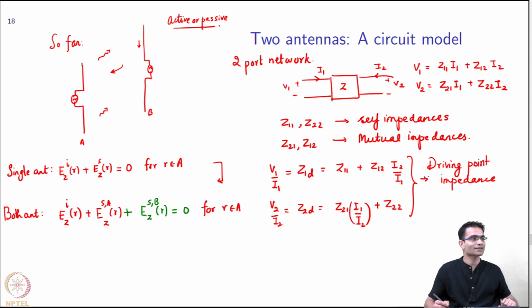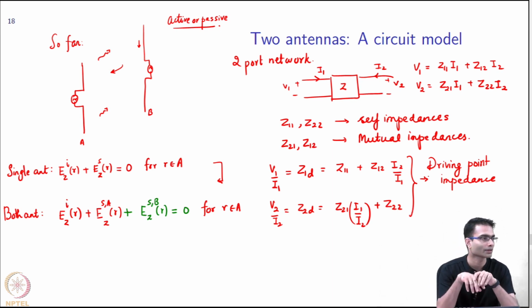So you can see that the driving point impedance depends on knowing I1 and I2. I need to know what these currents are, only then can I find out what matching network to design. So again, how do we calculate this? The induced EMF method, and various other methods, are used to approximate.